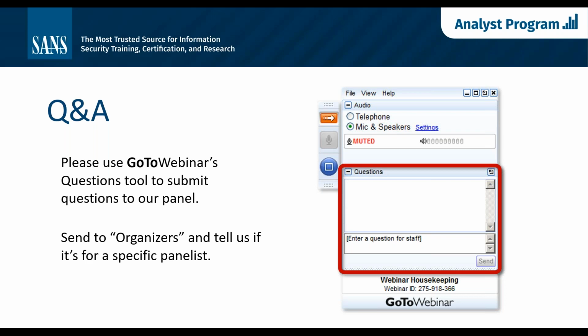This is Peter. I'd be happy to take that question. We typically don't see it at every level of the Purdue model. Obviously, the first step is between 3.5 and 4. You want to get that firewall in there to provide segmentation between the IT and OT organization, as Don mentioned. But we also see it and recommend it between 2 and 3.